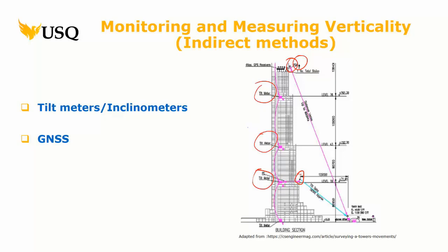So you're starting to see with this high rise, it's not a matter of just the surveyor on site, right? Setting out things. This has a data center that's collecting all this data. So tilt meters are one, right at the very top there. The reason it's at the top is because you can't see satellites from the middle, right? GNSS is ideal for continuous monitoring because it's a passive system. You know, unless someone shoots this satellite out of the sky, it goes day and night, right? And it's a very consistent system. Okay, so once you set it up, it's a great monitoring system.